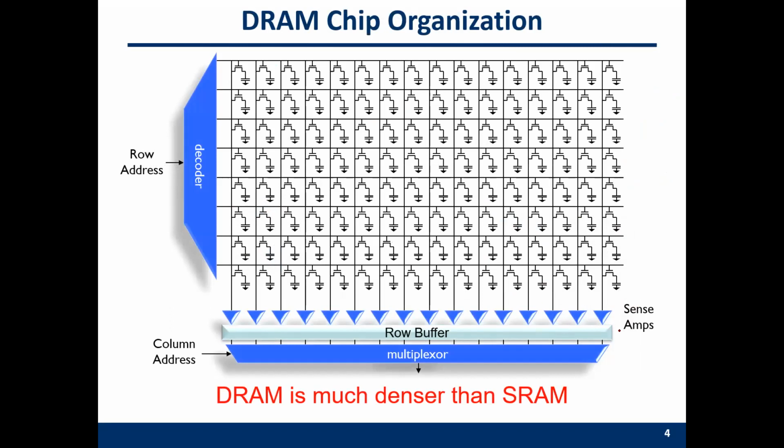Again, by the same array structure, we can have one array. So we have multiple rows and multiple columns. Each column is one single bit line, which is connected to the sense amplifier. Each row is just one page. We learned the concept of page in virtual memory. One page is typically 4 kilobytes.